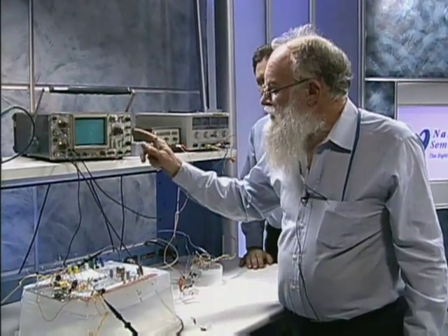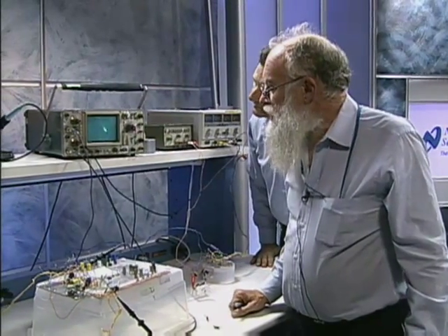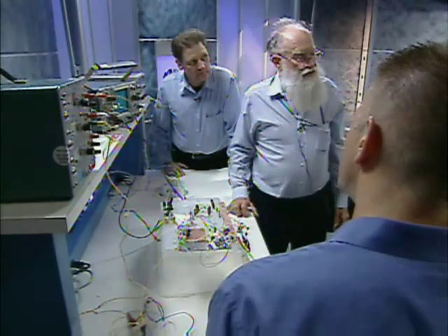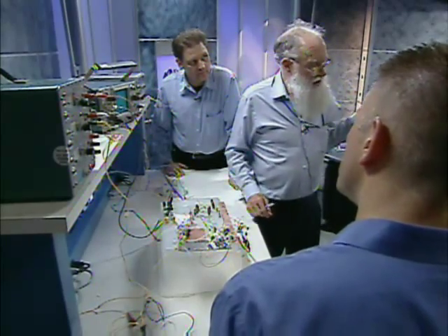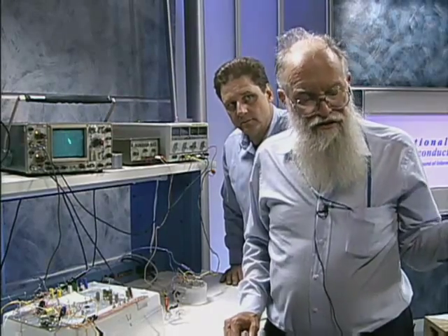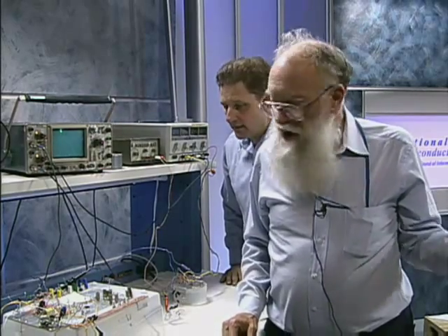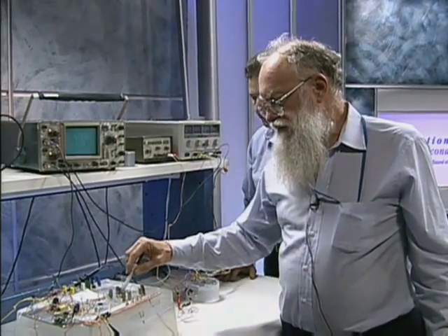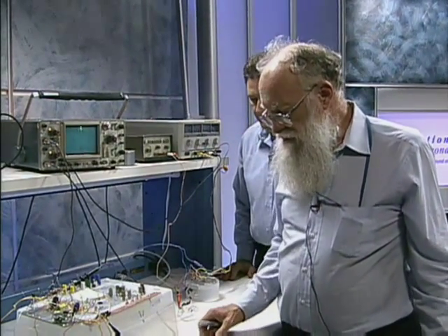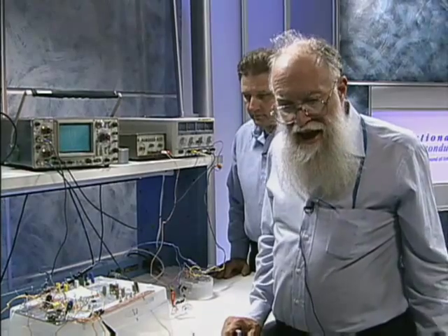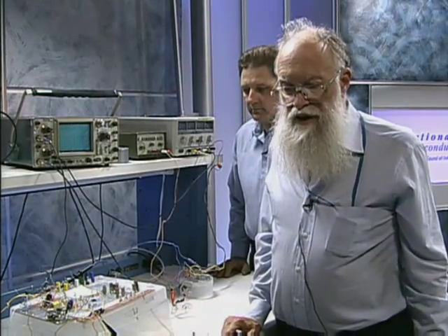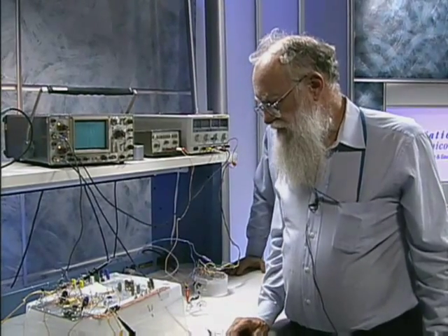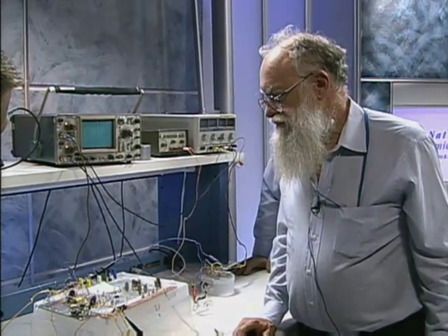We can move that around to detect small errors at about 3 hertz, because if you're doing it at 300 hertz, you're measuring inductance. At 3 hertz, you're measuring resistance. That's what we're trying to evaluate. Are these 2 resistors good? Yes. Do we have more resistors? Yeah, I got some 5 milliohm resistors, but I haven't got them here right now. We'll discuss that later. We can write that up and have it on the site. That's great.